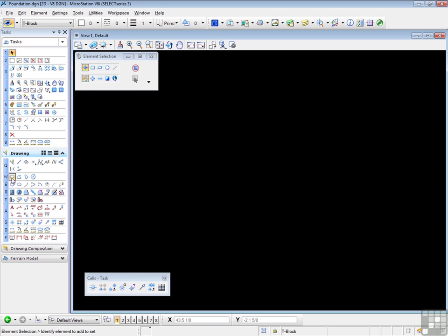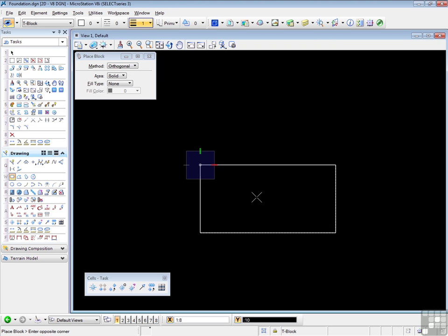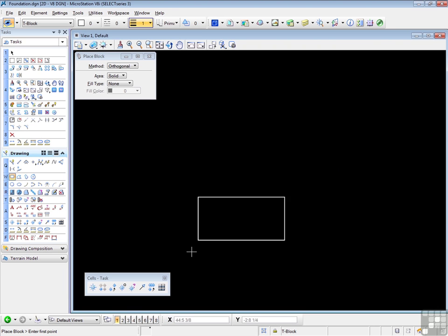I'm going to start with the block tool, use a weight 1 line, and draw my basic footer, which is 1 foot 8 wide and 10 inches deep. If you're working in metric, of course, simply look at the dimensions in the PDF file. So I need the width first, which will be 1:8, and down arrow and :10. There's my footer. That will do nicely.